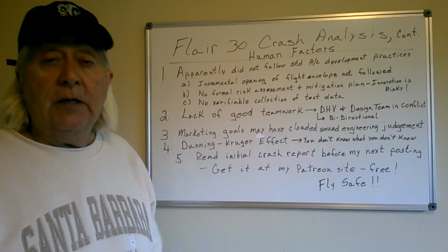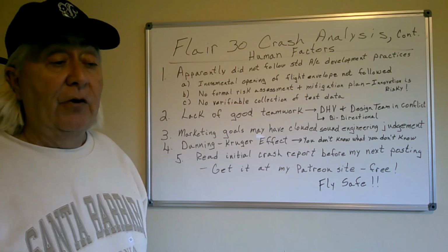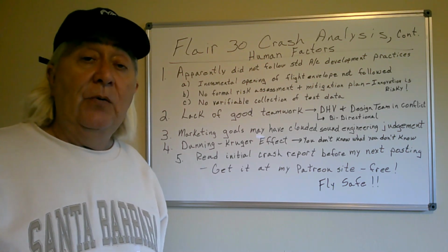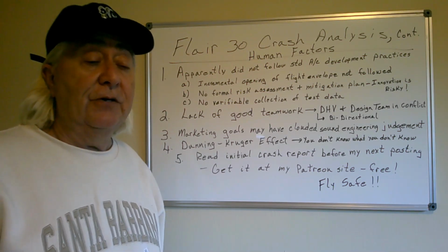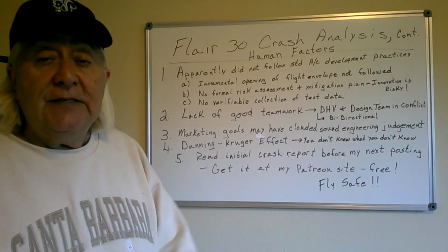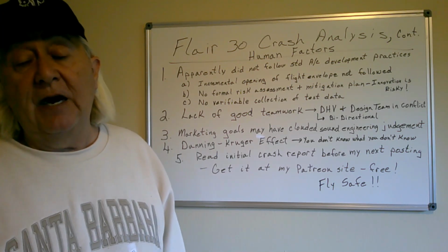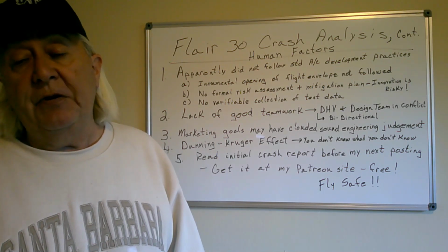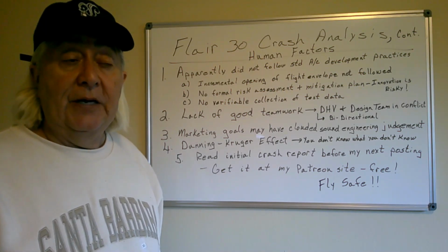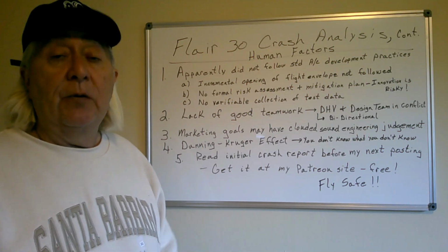But you literally have to say, like with my wing, I have a test program that says I need to be able to fly at 20 feet off the ground and hold altitude steady when on tow. I need to be able to roll the vehicle side to side without touching the wingtips on the ground. I have to have precise control, right, when I'm on tow. Well, we've done those. Okay, so the next thing is I got to get up high enough where I can get off tow and do gentle turns. Maybe banked 5-10 degrees, do a 30-degree turn to the right, and then come back to the left, and maybe a little bit of maneuvering in pitch. If I can do shallow maneuvers precisely, then we can move forward.